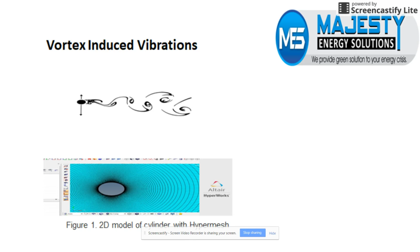The device captures the energy of vorticity, an aerodynamic effect called vortex shedding. As the wind passes through a blunt body, the flow is modified and generates a cyclical pattern of vortices. Once these forces are strong enough, the body starts to oscillate and enters into resonance with the lateral forces of the wind. This is also known as vortex induced vibration. Instead of avoiding these aerodynamic instabilities, our technology maximizes the resulting oscillation and captures that energy.